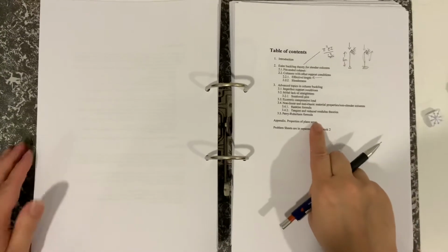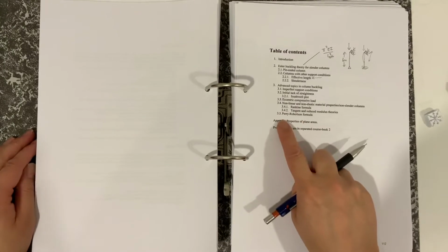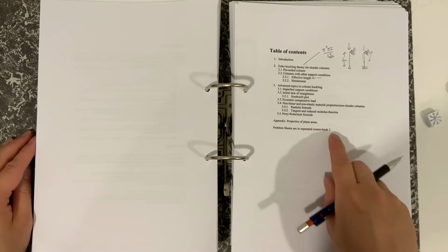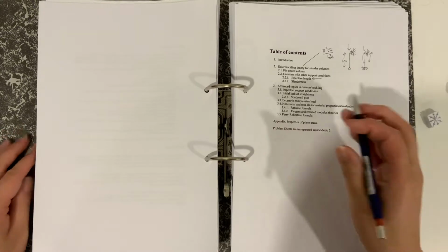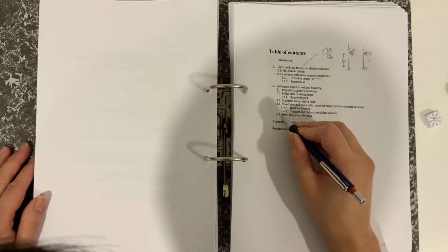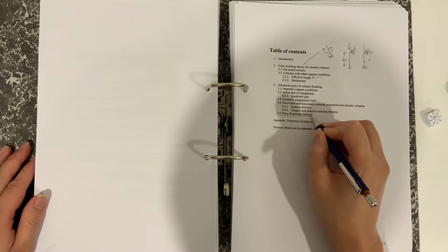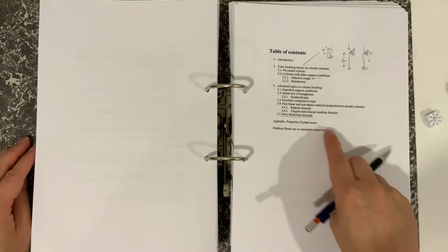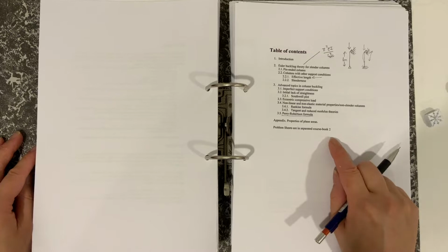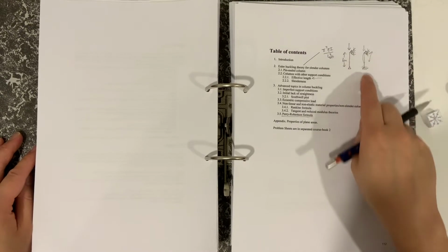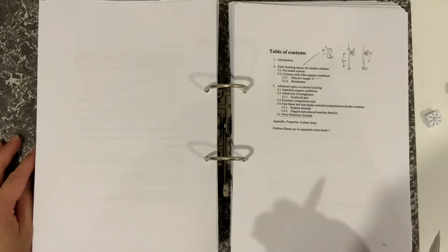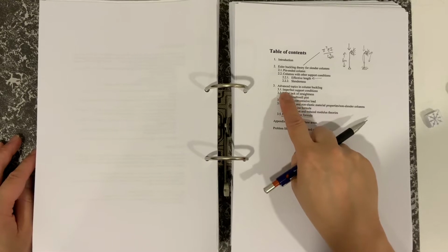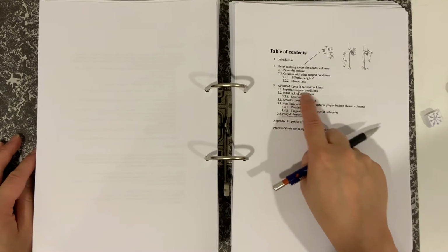Later on, we'll be talking about the design standards. The New Zealand design standards, like most of the other standards for buckling, use the Perry-Robertson formula. Basically, there's no such thing as a perfect column. This is all very idealized and very elastic, but in reality, some columns would be imperfect. They wouldn't be perfectly straight.